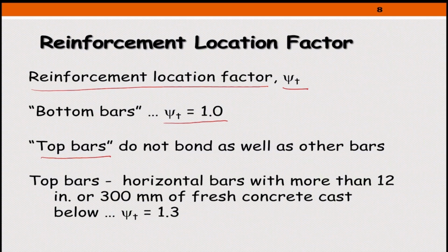But why? What is the rationale behind this? Think of a concrete section like this at the time of placing the concrete. We already have these bottom bars. You keep pouring concrete here, and therefore concrete around this is very condensed compared to bars on top. Because as we keep condensing concrete when we're placing it, perhaps there will be some settlement underneath the top bars.